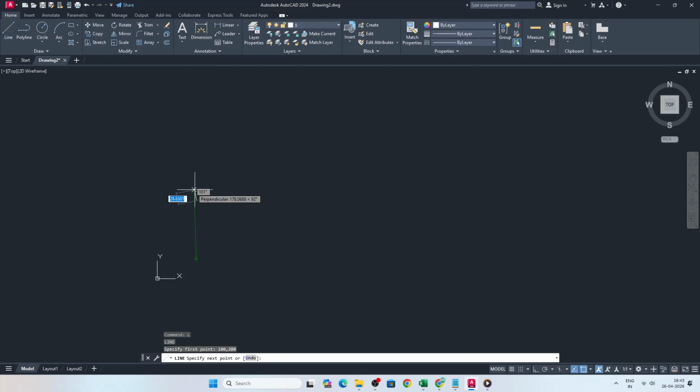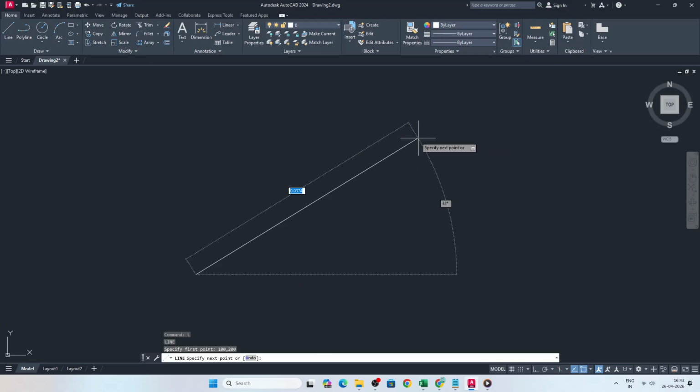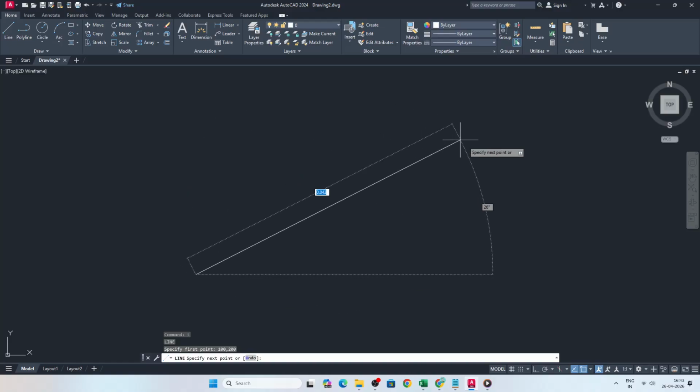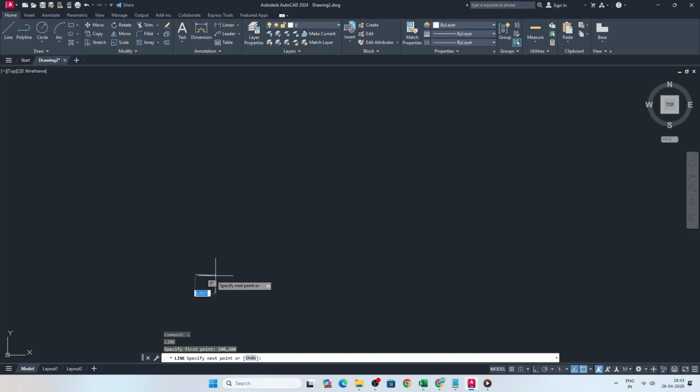This is a reliable way to keep your geometry accurate when you are mixing different input methods or snapping around. You can continue defining more vertices the same way. Each time you want an absolute location, just enter X, Y, and include the hash when dynamic input is active to avoid accidental relative entries.